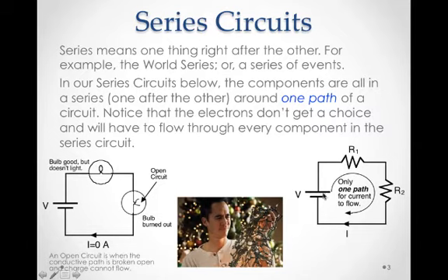So right here, again using conventional current flows from positive around to negative, and this long battery terminal is the positive side, and so the electrons will have to flow through this resistor and back to the battery. There is only one path for current to flow. That's probably the biggest idea of series circuits.